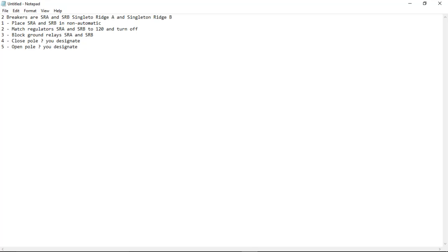Right. Once that is complete, you need to go backwards in what you just did. 6. Unblock ground relay SRA and SRB. What else? Turn on the regulator. That's all you have to do there. They will go back to their normal operation. Good call there, Paul.